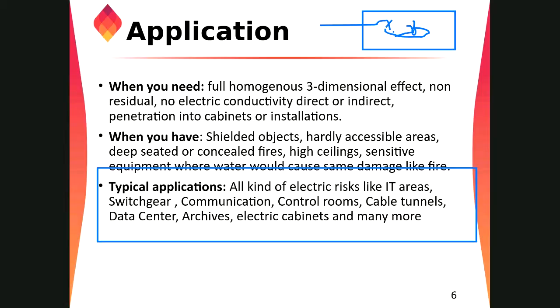We can use it in libraries, old heritage buildings or museums, right? We don't want to lose our products, our building, our building equipment. But if there is an actual fire, we need to protect it. We cannot protect that with water, because water again damages those products. So we need a clean agent system. Sometimes the clean agent system is the alternative for a pre-action system.